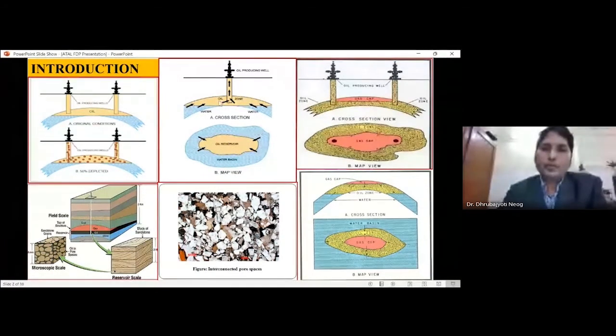So in this process of crude oil production, what happens is, from the aquifer, water will influx into the oil reservoir, and that will help in the displacement of oil with cumulative production, when the oil will be leaving the porous spaces of the reservoir rock to flow into the well. The influx water from the aquifer will maintain the reservoir pressure inside the reservoir. Therefore, pressure can be maintained in this type of reservoir for a very long period of time and at very high pressure.